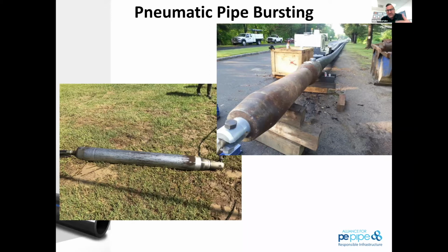So in order to maximize the tool size, that 14-inch hammer mounts out in front of the head. And then that is, I believe, a 16-inch ductile iron pipe size HDPE behind it. So that shows you the scope and scale of what we'd call a small diameter head that's going to do 8 to say 12-inch, and then a mid-size head that's in that 15 to 18-inch range.